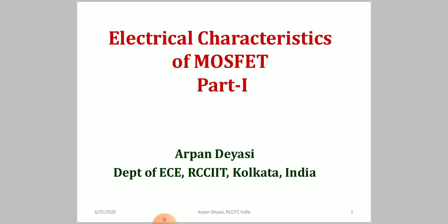In lecture 4, I showed why the MOSFET is also called a 3-terminal device, not a 4-terminal one, because of the body effect. And what is the role of the body effect? I showed it with the formation of virtual diodes. I also showed why source and body are shorted for both p-type and n-type substrates. Also, not in great detail, but at least qualitatively, I mentioned the enhancement mode and depletion mode MOSFETs. So these points are already covered.